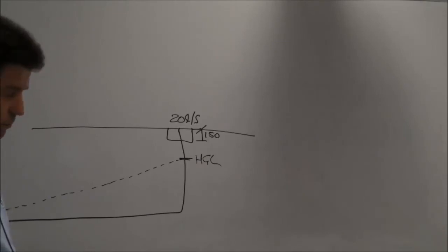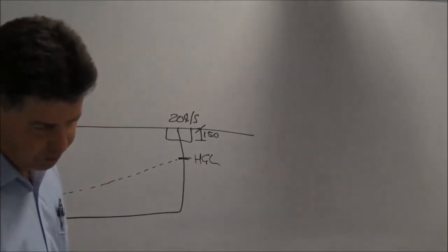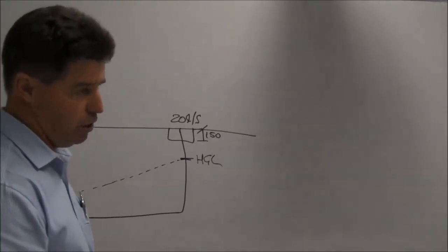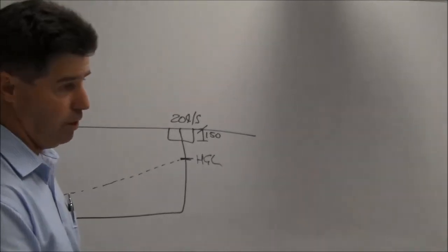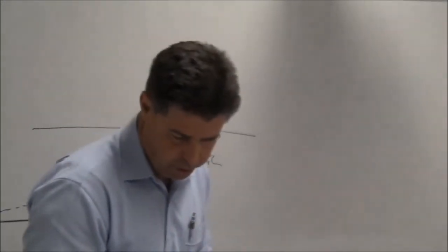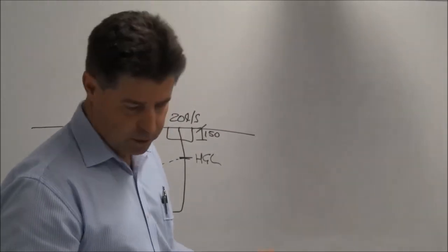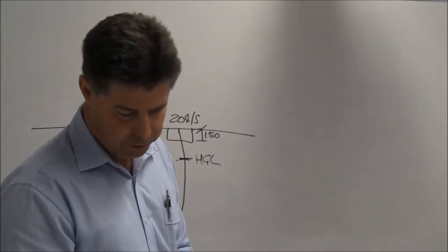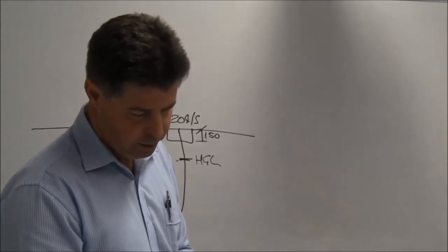Where does the point where the hydraulic grade line starts come from? It depends, again on page 21, have a look. For example here we've got a 150 pipe. If you looked at the chart, a normal 150 pipe is running at 18 point something litres per second at 1%. That's the normal flow rate. But all I've done here is given you a pipe of 150 over a length of 22 metres at 28 litres a second. So our friction slope is 2.42%.